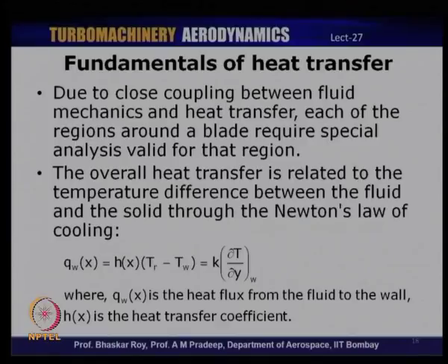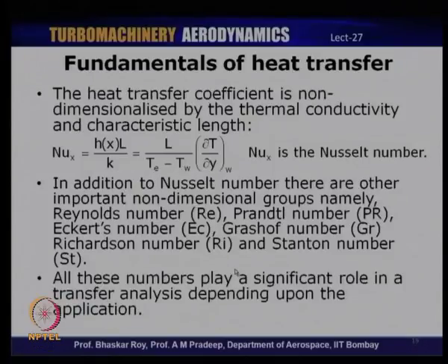Now, in general, one can write the overall heat transfer, which is related to the temperature difference between the fluid and the solid, through Newton's law of cooling, which relates the heat flux, which is mentioned here as Q_W, that is heat transfer from the wall, is equal to the heat transfer coefficient h multiplied by the temperature difference, and this is again related to k times dT/dy, which is the temperature gradient.